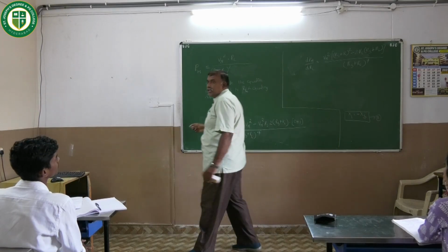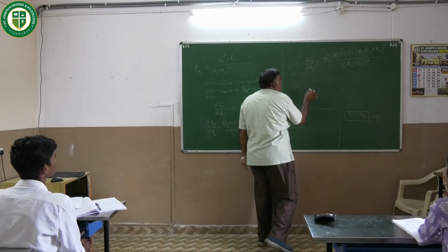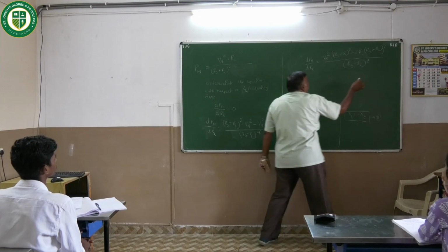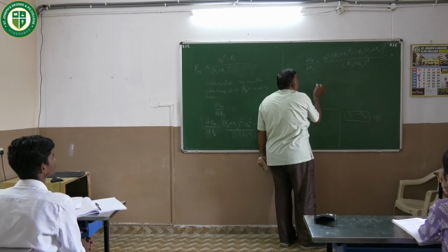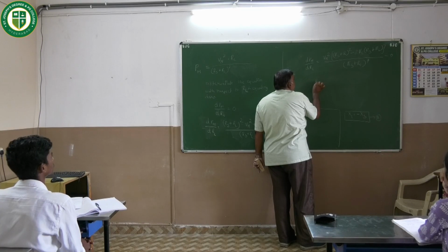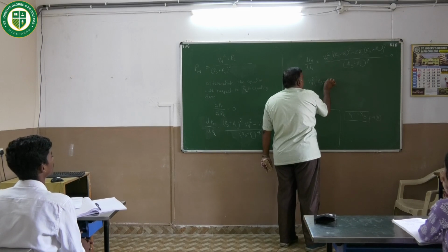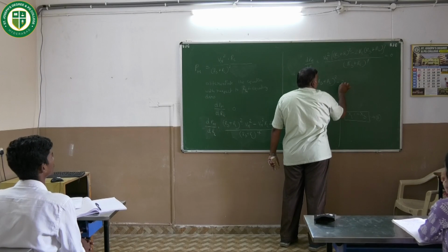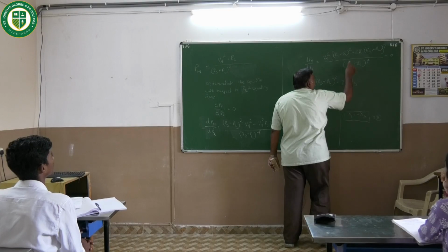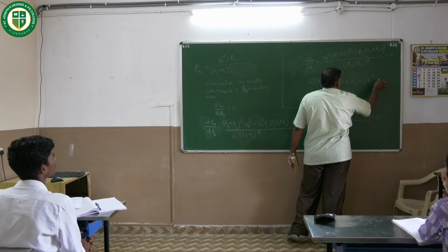Now after the differentiation, again you need to equate the equation to a 0. So when I equate to a 0, if I cross multiply, denominator is going to become 0. So what you left out is Vm square into Rs plus RL whole square minus 2 RL into Rs. Minus of plus is minus, it is going to be 2 RL square is equal to 0.